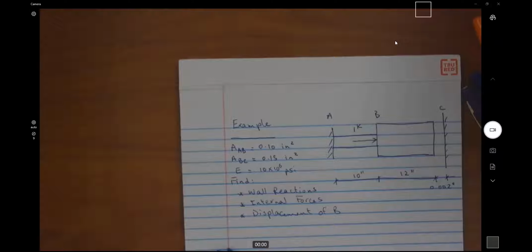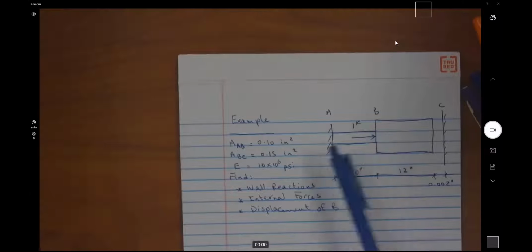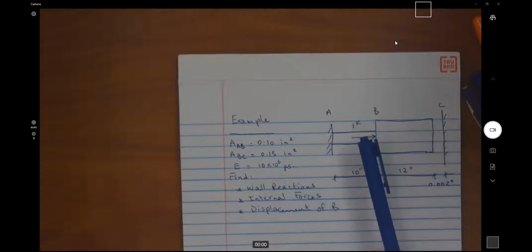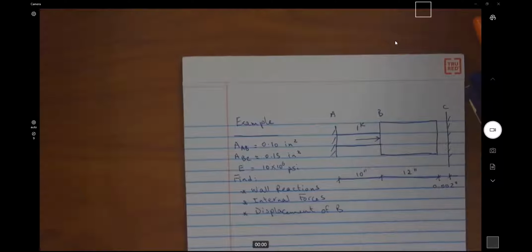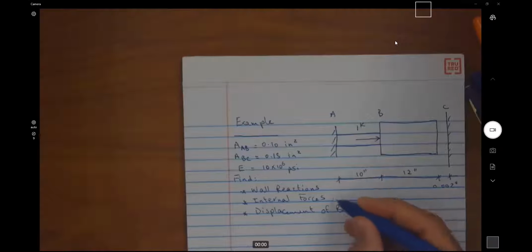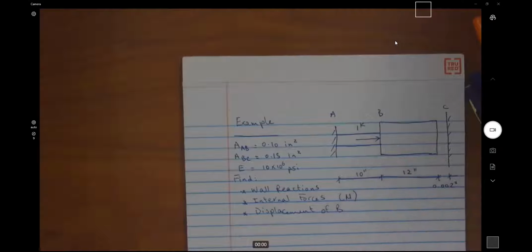And when we are mentioning here tension and compression, we are thinking of these as axially loaded members, but we never mention bending, we never mention torsion. So these are behaving, each of them, like a two-force member that is either in tension or in compression. They are axially loaded members. So when we are thinking here internal forces, based on our analysis of what's going to happen, we are looking at normal forces. No moments, no torques.